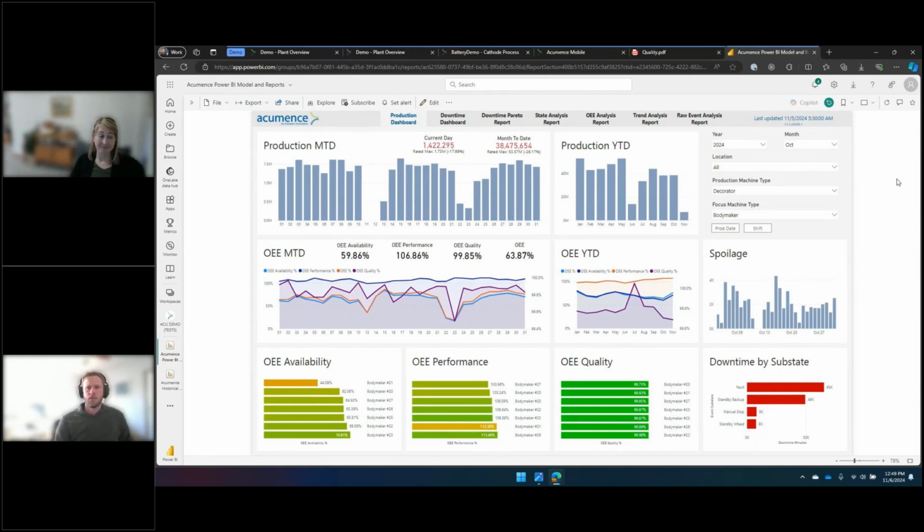If you're tracking all of that in a tool control system and integrating that data with your production data, your defect data, and things like stroke counts, you can say, based on historical changes, you're at 80% of the typical strokes this body maker runs at before it needs a tooling change, and you're starting to see an increase or an abnormal short can rate.